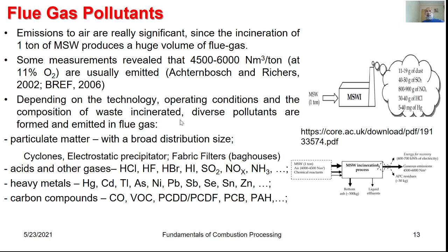Depending on the technology, operating conditions and the composition of the waste incinerated, there would be diverse pollutants emitted in this flue gas. So there would be a broad range of particulates, which need to be controlled through cyclones, ESPs, and certain baghouses. There would be acids and other gases which need certain cleansing mechanisms. Also, the heavy metals and carbon components will be in need of certain specific treatments.